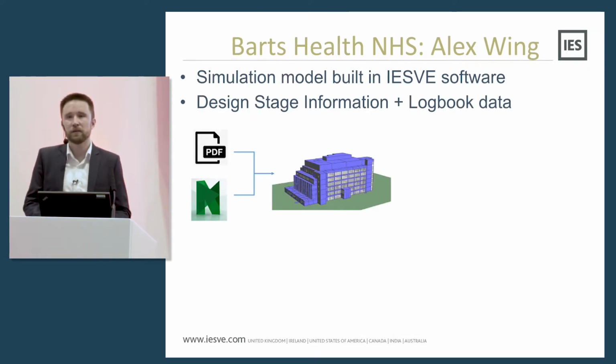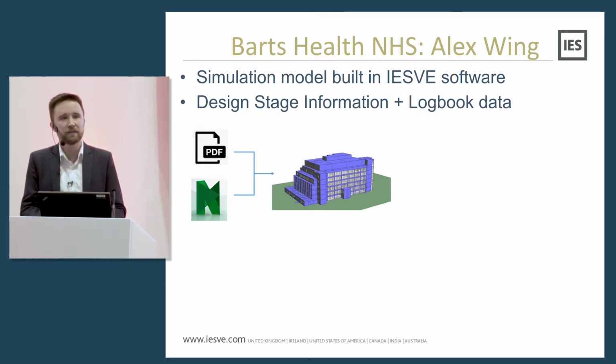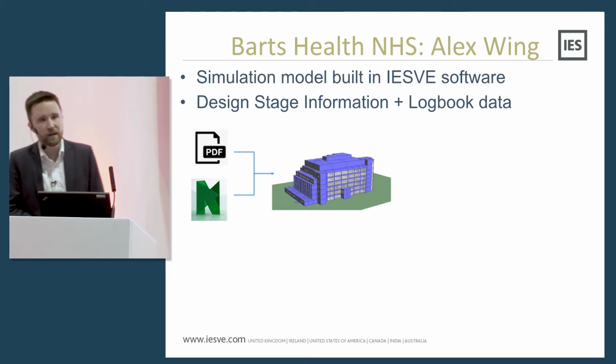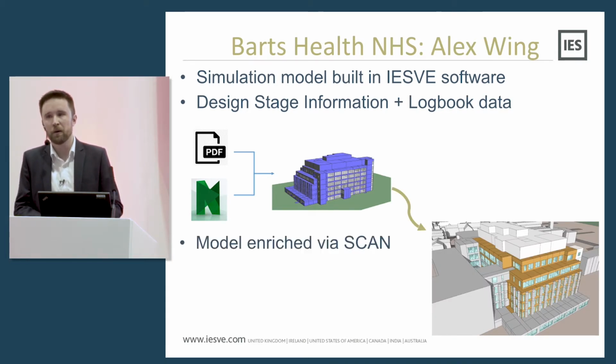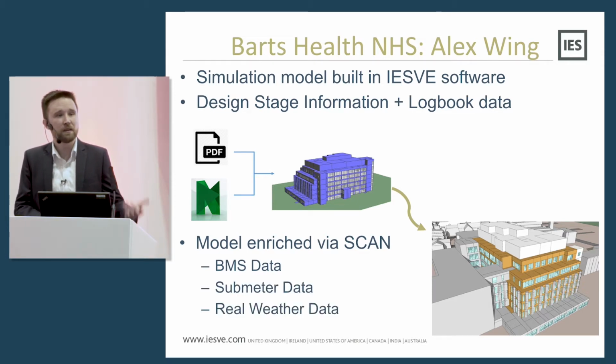The process involved, unfortunately, the design stage models weren't available to us, so we had to build a model ourselves from scratch based off the design stage documentation. We then started to leverage the data that was coming from the building system. So using the SCAN portal, connecting to the model, we took in things like the BMS data to refine schedules in the model to make it a closer match to the building.